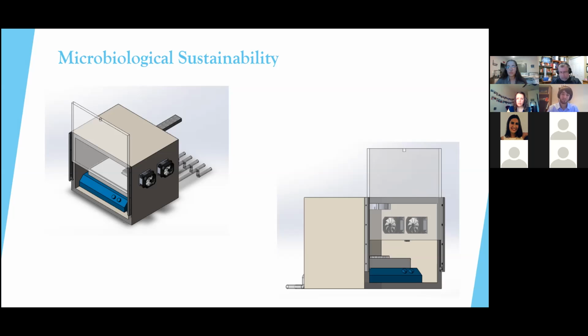Each mass flow controller is connected to its respective canister via plastic tubing, and it's directed towards the environment as well. Each mass flow controller, so one is connected to oxygen, another one regulates nitrogen, another carbon dioxide, another methane, and the fifth hydrogen. The fan, there's a centrifugal fan attached to the top of the system, which is meant to expel any excess gases out of the system, out of the environment and out of the general system.